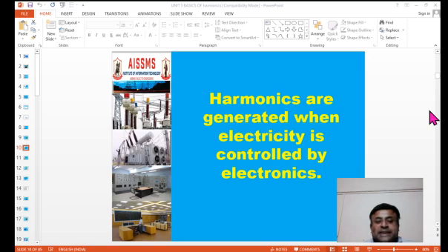The loads at residences were fans and lights, like that, which were totally linear, and therefore for a very long period, up to 1990, there were no such nonlinear loads to the extent to create harmonics, and therefore the problem of harmonics could not be realized at that time.